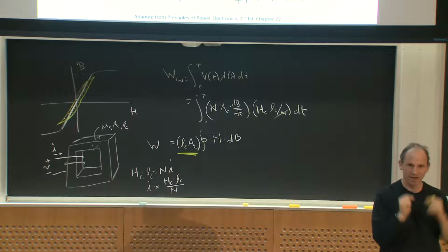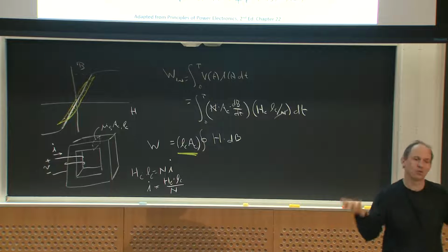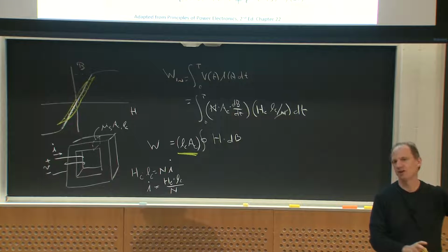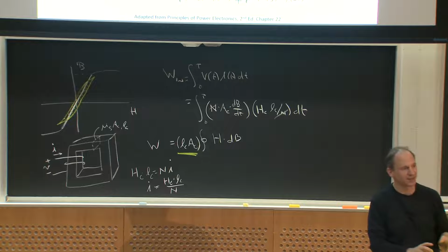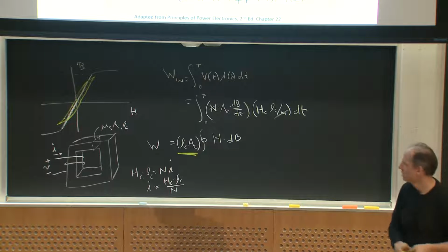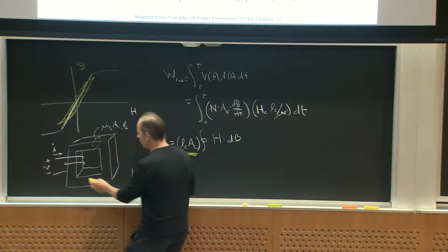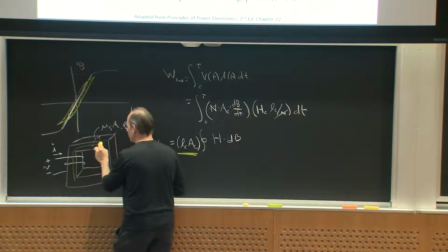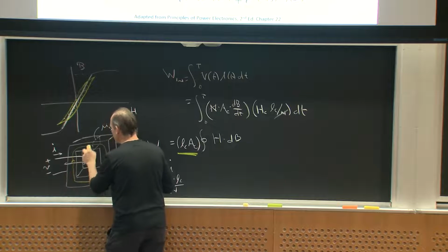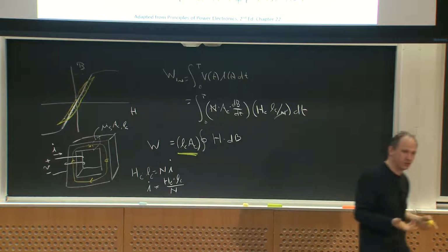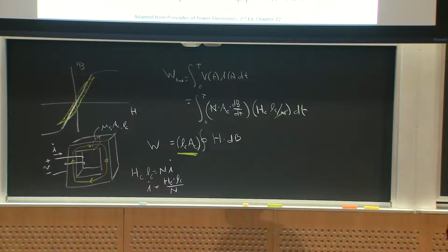I should say that this kind of loss owing to the magnetic domains is one form of loss you can get. There are other forms of loss you can get, however, in cores that are not so-called hysteresis or related loss. And one of those is, in fact, eddy current loss in the core. Think about this. What is this core doing? If I put a current in here, I'm putting a flux and a flux density of B through the core itself, right? Well, at low frequencies especially, we often use conductive magnetic materials, right? We use steel. Steel's pretty conductive.